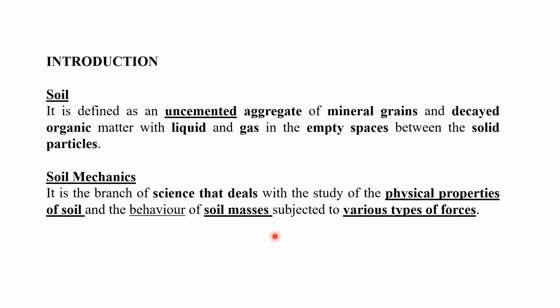So what I'm trying to say here, we have to test the physical properties of the soil, which is available below the base of the footing, so that we could know the bearing capacity of soil. Without knowing bearing capacity of soil, we should not design the foundation, right? So these two things, physical properties and the various types of forces subjected to the soil mass, should be studied.